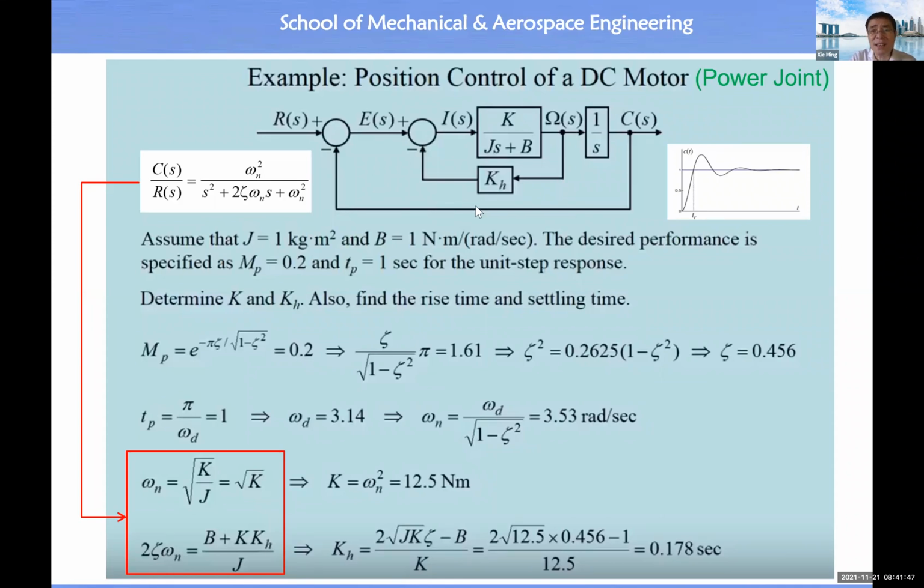The beauty of this design solution is to make use of the error signal to serve as the desired velocity. This makes sense in physics. When the position error is very big, we need to quickly reduce the error. Quickly reducing the error means what? Set the desired velocity to be very big, so it will quickly converge to zero. Therefore, we use the error in position to serve as the desired output from the velocity control loop. When the distance becomes smaller, this will be small, so it makes sense for us to slow down the motion.